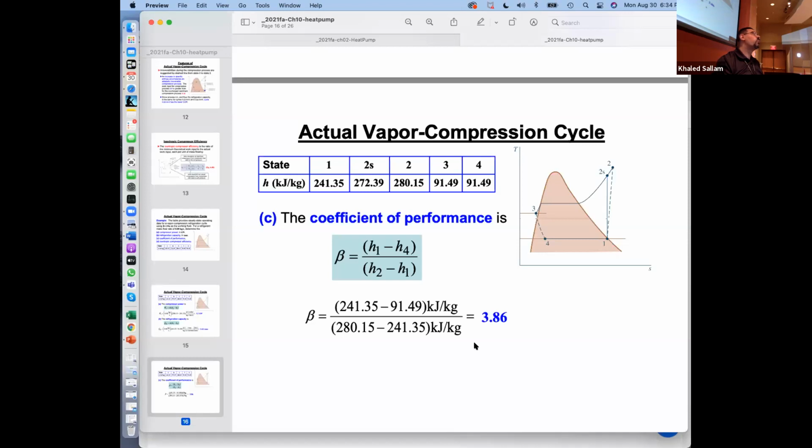I'm clarifying, the product that you look at is one that advertises some standard COP. Do you think they got that number from taking the average difference? How do they calculate that? I think they have to specify the temperature, and they do. If you read the blueprint, you will figure out what temperature they tested at.